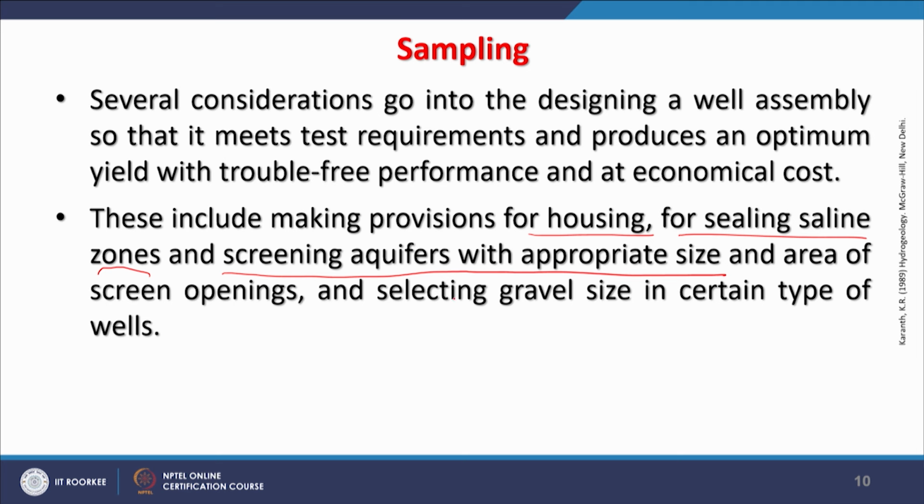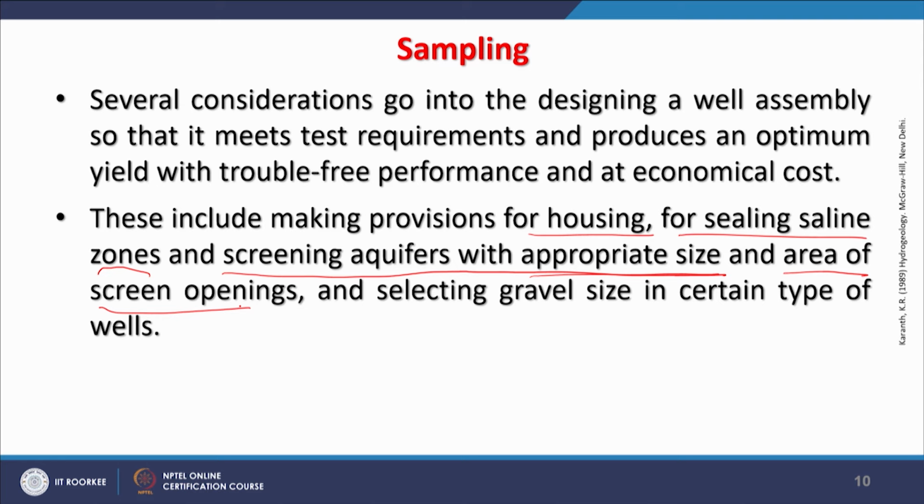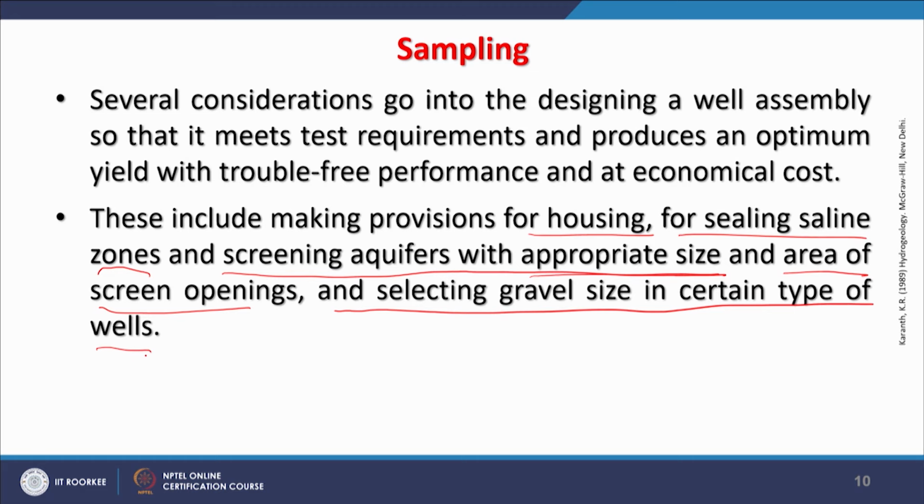Screening pipes are required, and then we have to choose their size and the design of the screening also. The area of screen opening, how much is open towards the formation so that water can enter into the well. Also, we should know what kind of gravel size is needed for packing, because between the pipe and the well some packing may be required. So, that gravel size has to be of a certain type.